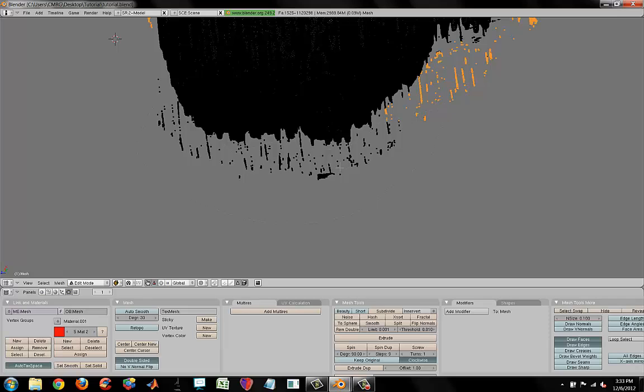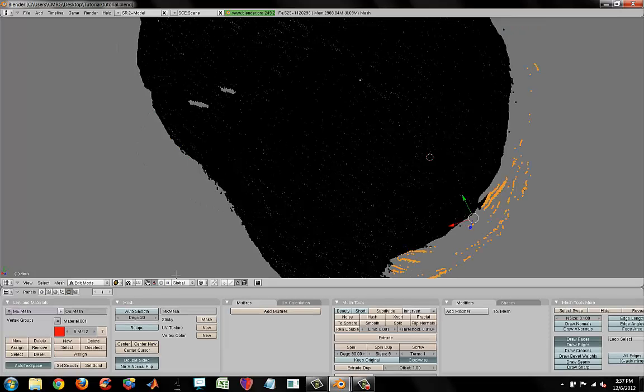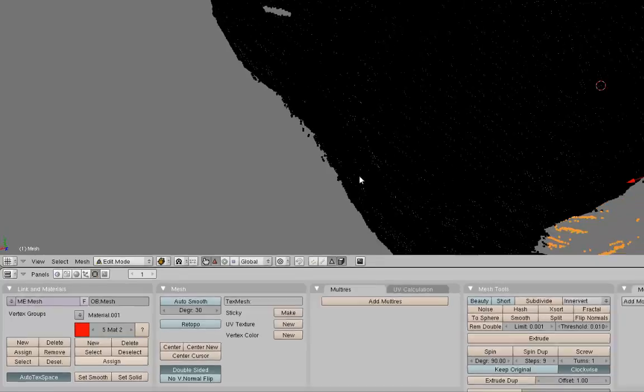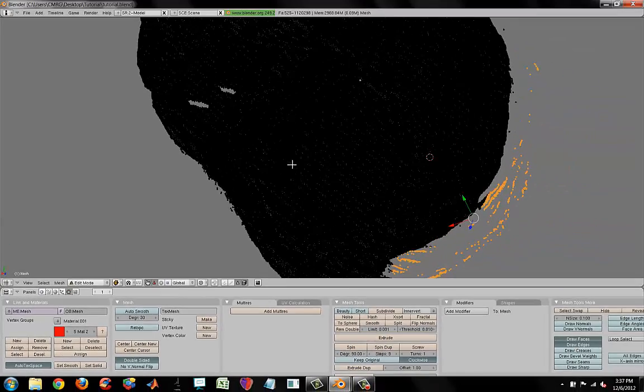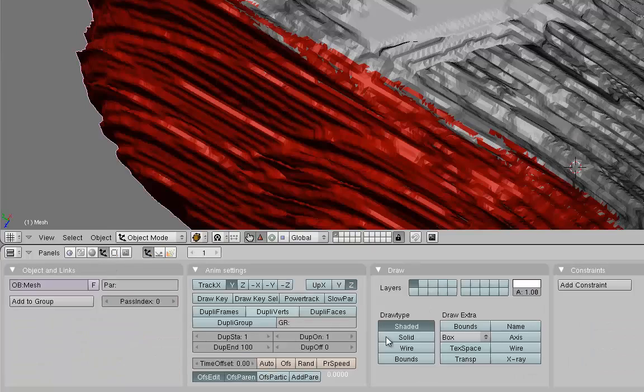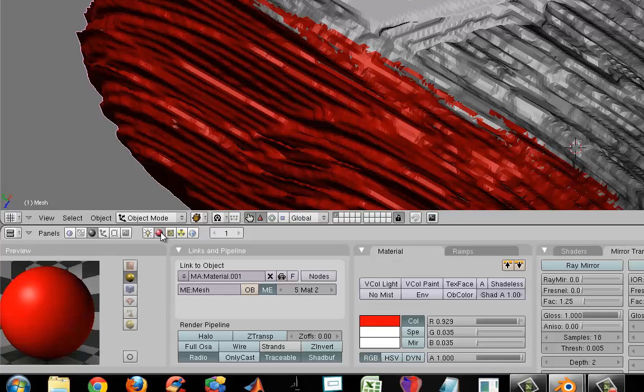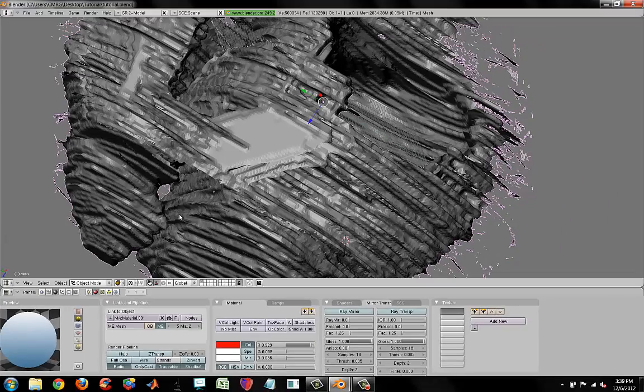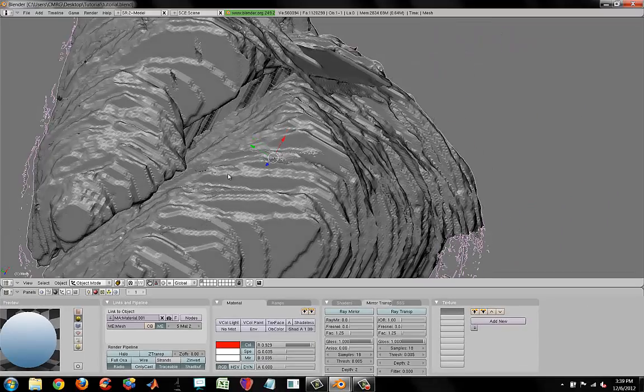When I'm happy with the assigned myocardium, I also want to hide the myocardium in the Object mode to have the same layout in both modes. For that, you have to turn on the transparency on Object and press Trans. Then on Shading, you have to turn on the material buttons and set alpha to 0 through this cursor. Now we can distinguish both ventricles.